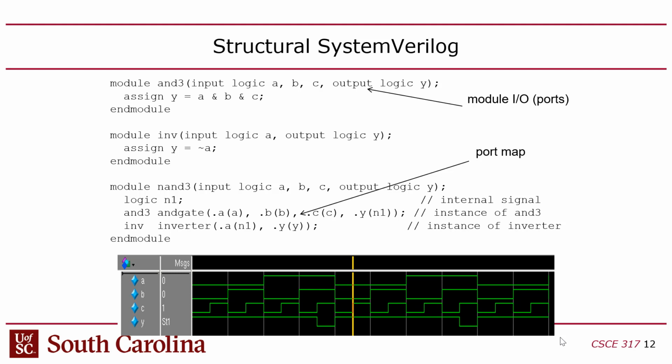So they have 4 analog channels that basically act like an oscilloscope. And then they have 2 16-bit ribbon cables that you can plug in to connect the digital signals, and that's the logic analyzer feature, right? We still call these oscilloscopes, but technically they're oscilloscope and logic analyzer. Does it make sense? So logic analyzer is binary, 0, 1. Oscilloscope is you're measuring voltages, analog voltages.